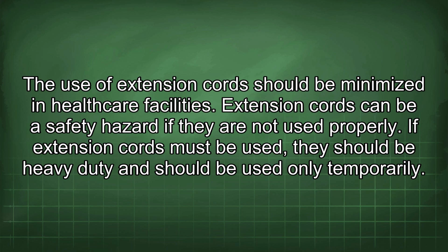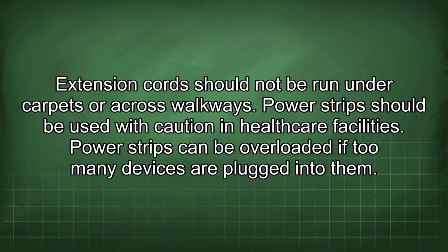The use of extension cords should be minimized in healthcare facilities. Extension cords can be a safety hazard if they are not used properly. If extension cords must be used, they should be heavy duty and should be used only temporarily. Extension cords should not be run under carpets or across walkways.